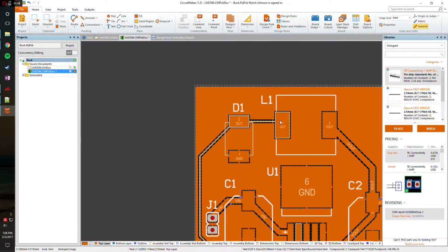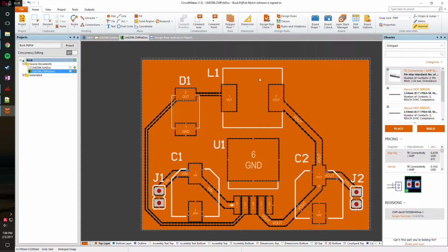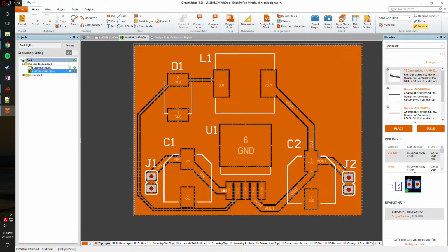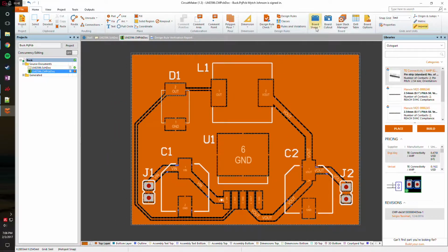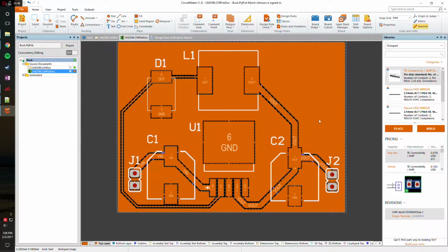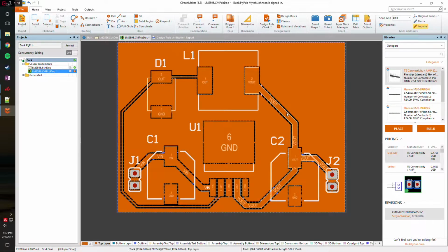Okay, that was the first thing, and then the second thing was I forgot to tell you guys. Once you have your PCB and the size set, you actually want to define the outline of it, and that will be done automatically. So I know that I can't make this any smaller. It looks good to me. I'm going to go to board shape and create primitives from board shape. Everything there looks fine. I never really mess with that. And we're good to go.